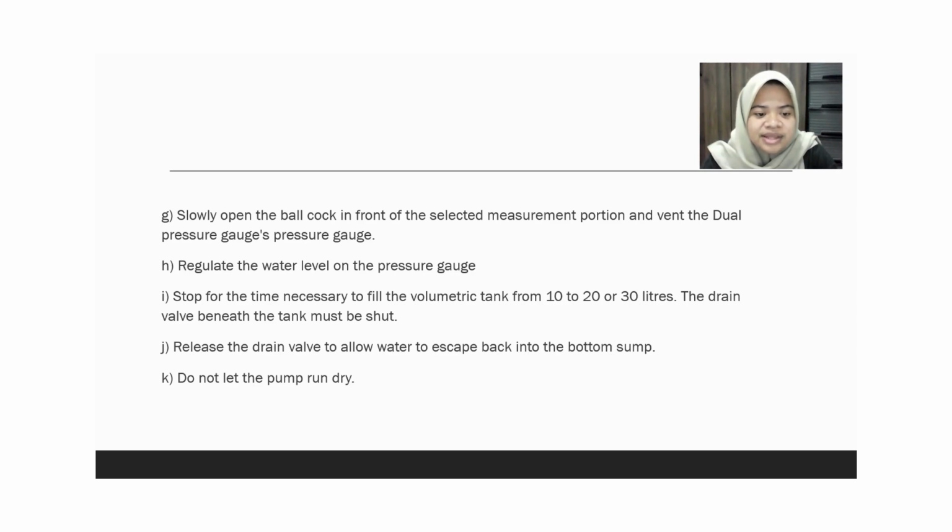Stop the time necessary to fill the volumetric tank to 10 to 30 liters. The drain valve beneath the tank must be shut. Release the drain valve to allow water to escape back to the bottom sump. Do not let the pump run dry.